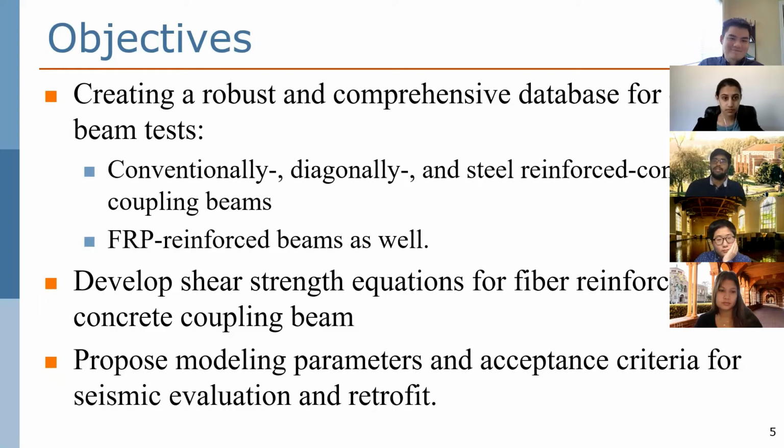The objective of the steel fiber reinforced concrete coupling beam modeling is to develop a shear strength equation, and currently we have 38 test specimens for that. So the goal is to create a shear strength equation and later on move on to propose modeling parameters and acceptance criteria for seismic evaluation and retrofit, which is ASCE 41.